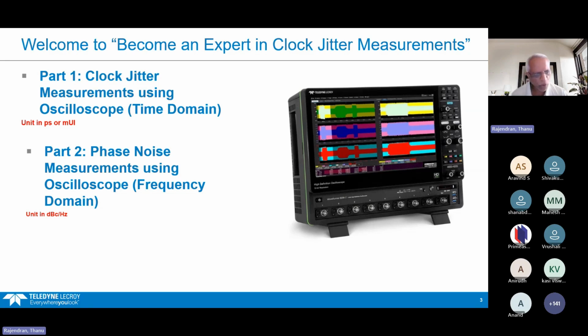Like I said, the clock has to be analyzed in all respects, in both the time domain and frequency domain, for you to make sure that the system works very stably and without any errors as far as the BER is concerned. Going down the line, we see that jitter is one of the main issues that can arise because of many factors. As I go through the slides, you will see why we say that.